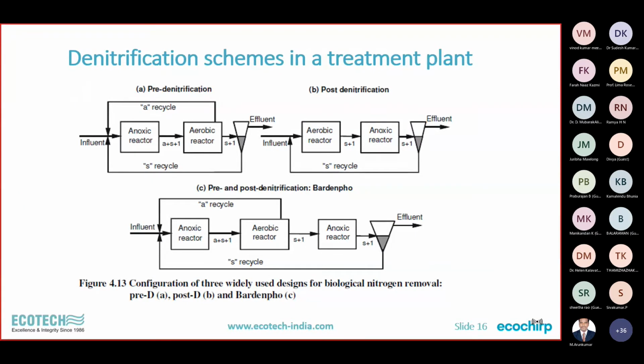They wanted a nitrogen level of less than 1 ppm in the effluent. In which case, these technologies, these techniques may not be the best suited. We went for the Bardenpho process, a 5-stage Bardenpho process, where it was a 3 MLD plant. So depending on the size of the plant and the requirement of the treated water, you have to select the best technique or technology available, strategy again.